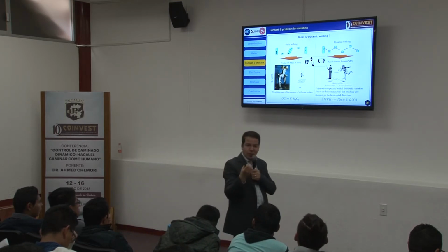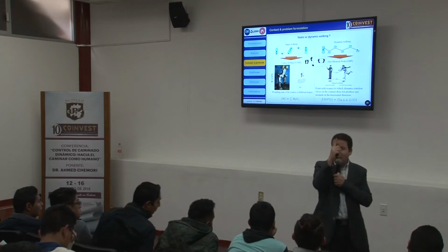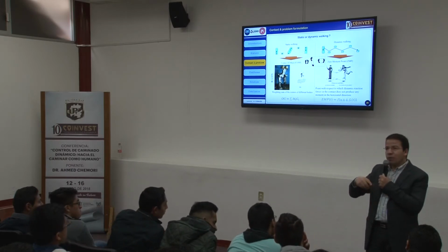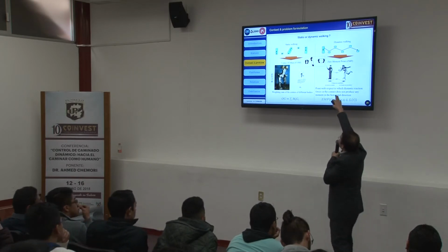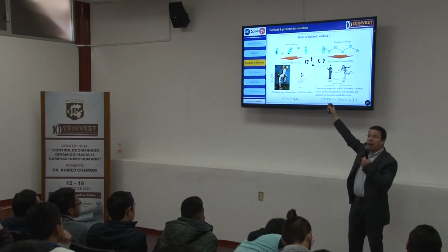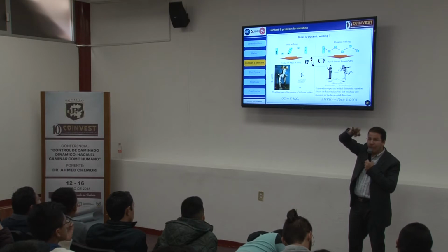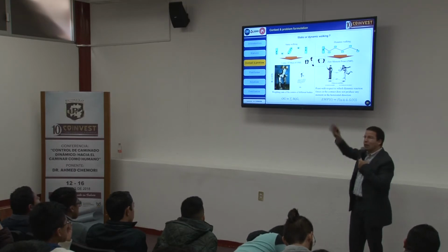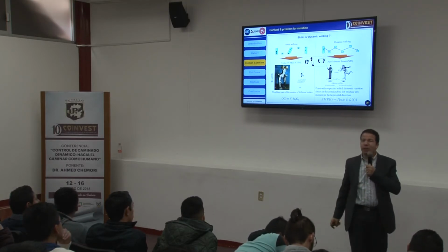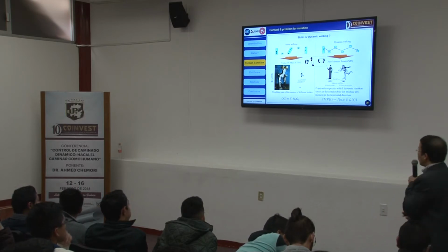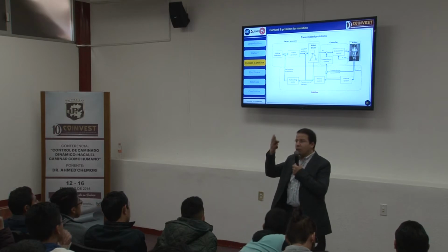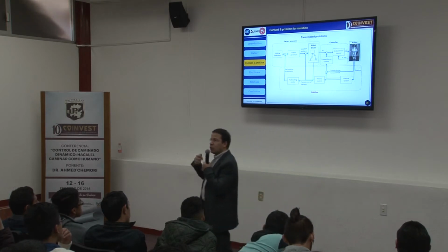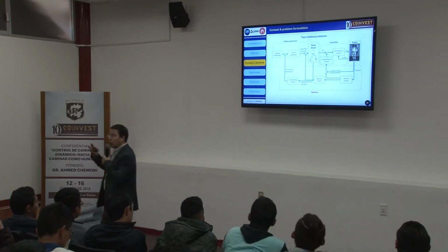And the idea is to keep this position of the resultant vertical forces inside the polygon of support during the walking. So you can have walking like this, where the center of mass is outside the polygon of support, but the ZMP all the time is inside. So we can guarantee the stability of the dynamic walking. Nice.